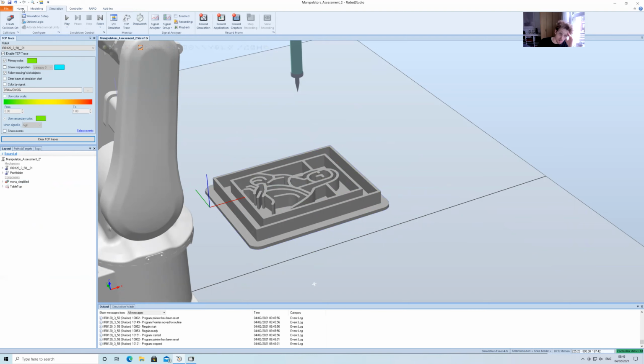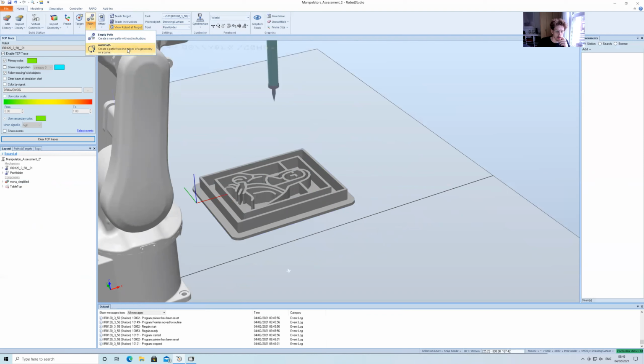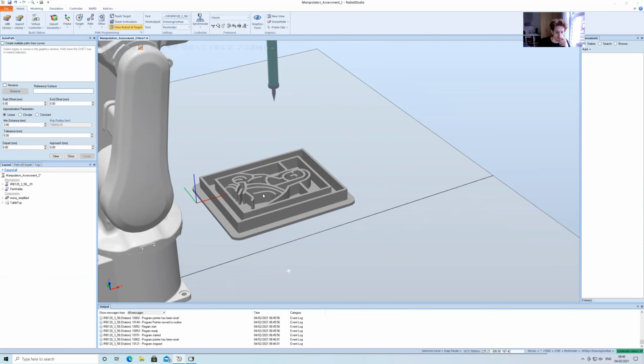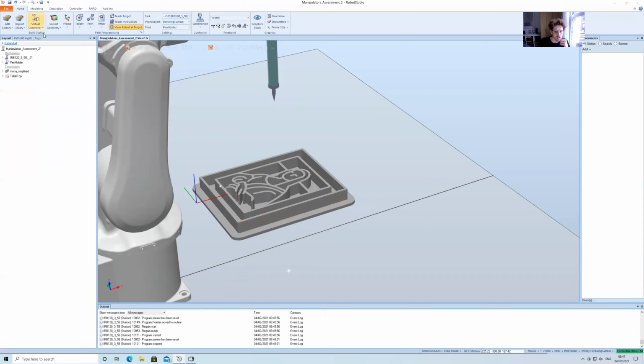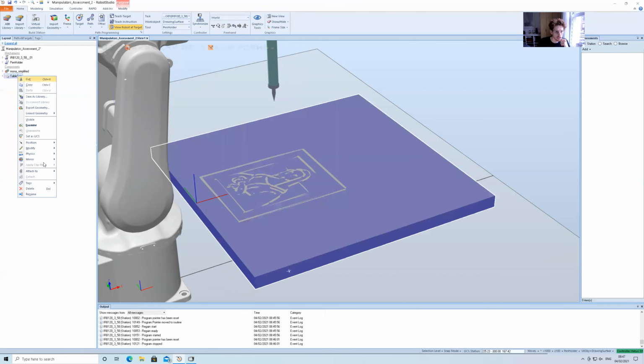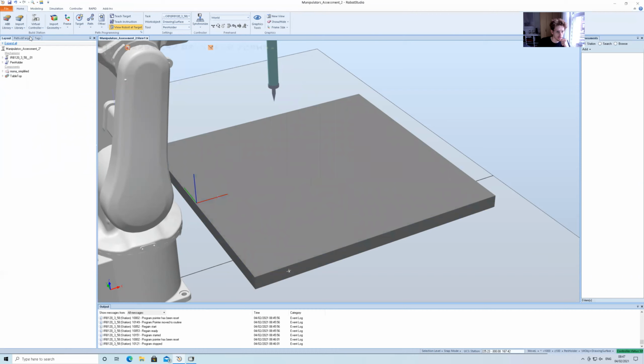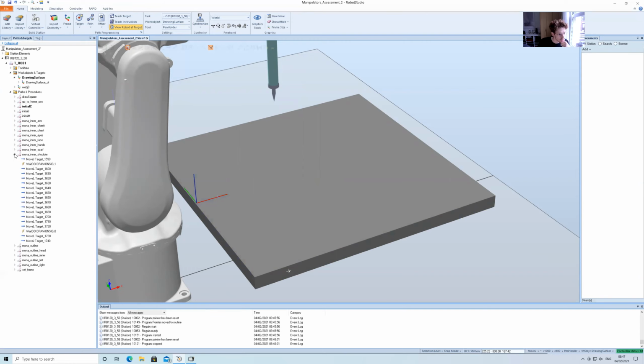Using a tool in ABB Robot Studio here, on the Home tab, there's an auto path, and you can select and it will generate paths for you, which is a lot quicker. This is quite a complex drawing, so there are tons of paths and targets made. I've labeled them so they're easier to understand, but each of them consists of a ton of paths.